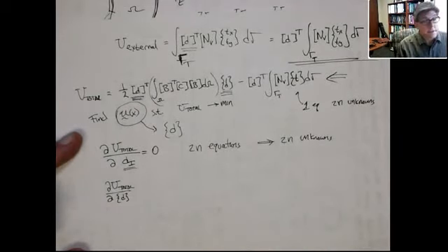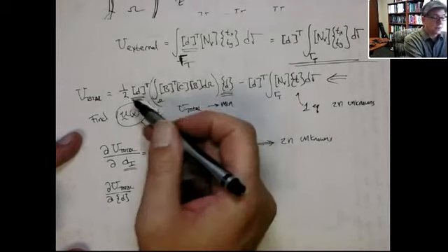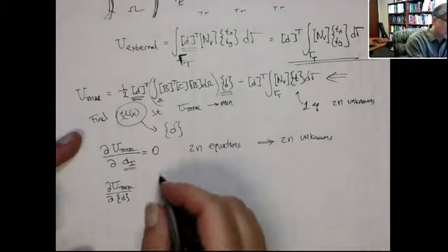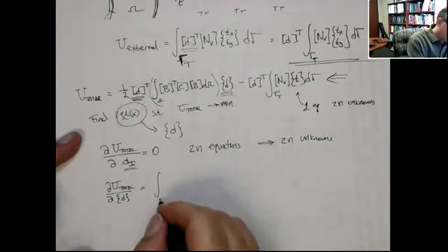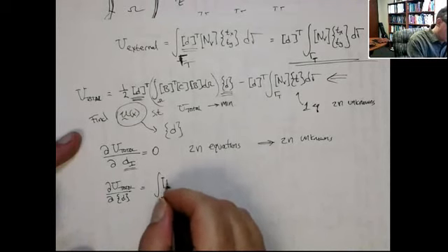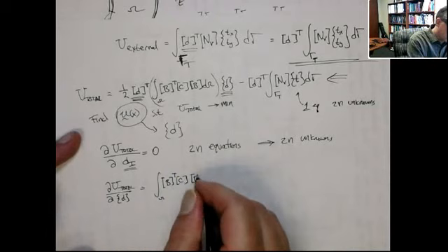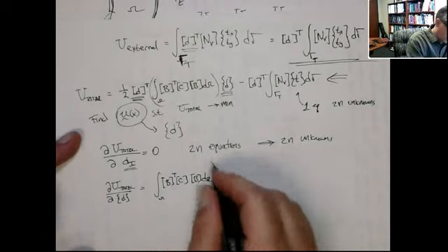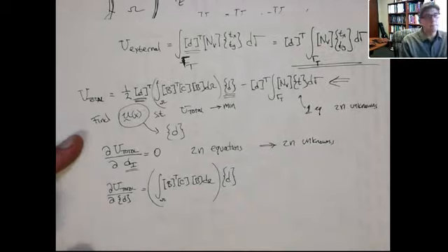So that acts like a d squared, so you get a 2, which cancels out the 1/2, and then you're just left with the integral over omega of b transpose times c times b d omega, this quantity, multiplied by d, right?